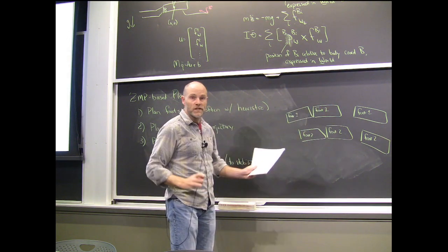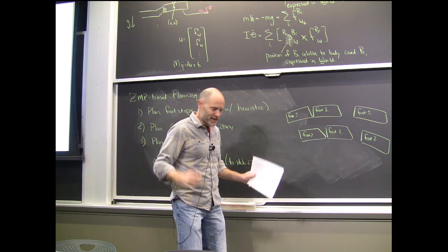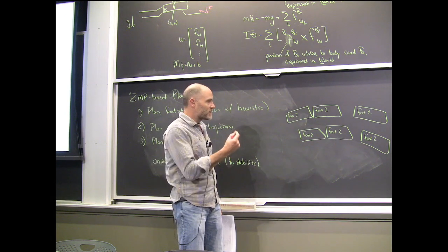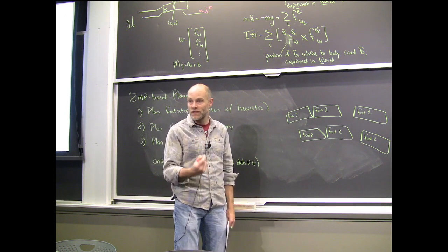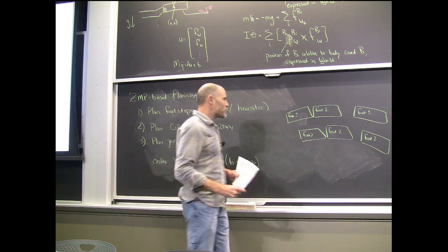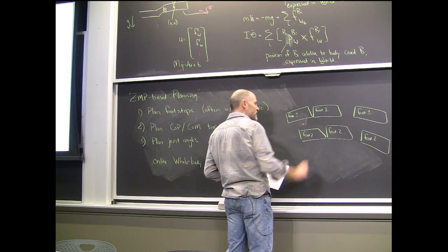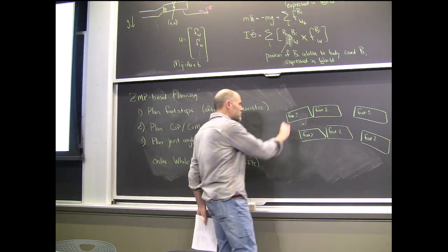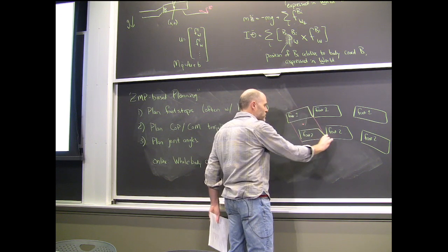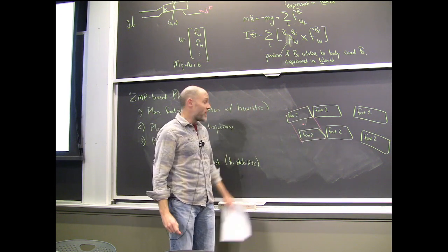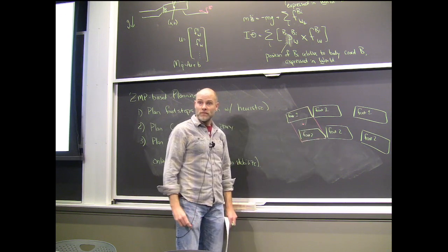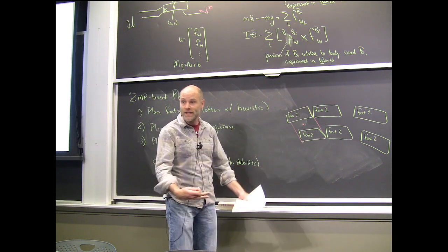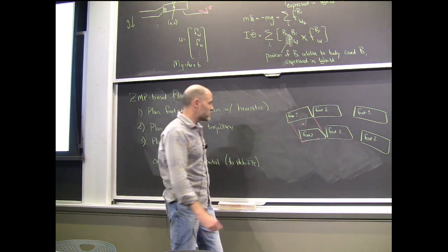If we think of ourselves as being likely stable, maybe even having some metric for unexpected disturbances, based on having my center of pressure closer to the middle of my foot, then a natural thing to do would be to start with my center of pressure directly in the middle of the support polygon. So when I'm first standing still, I'm going to go like this. Then I'm about to lift up my first foot, and I'm going to plan this the same way we gave a mode schedule to make the problem easier before. Here we're giving the footstep schedule to make the planning problem easier.